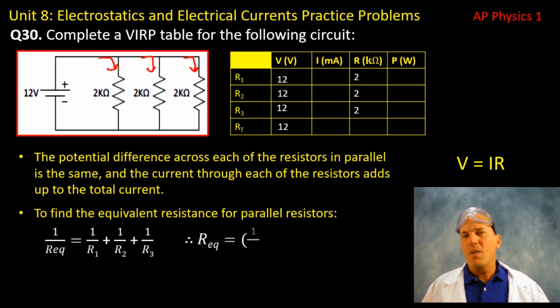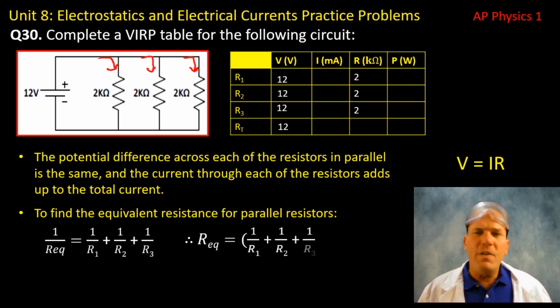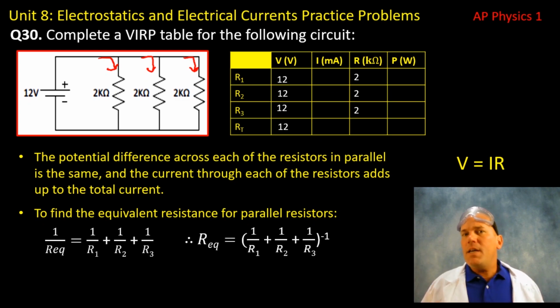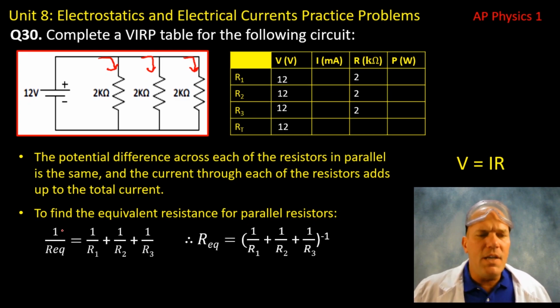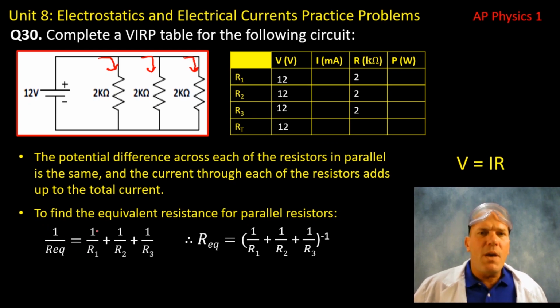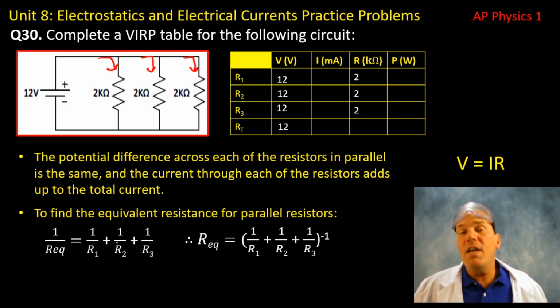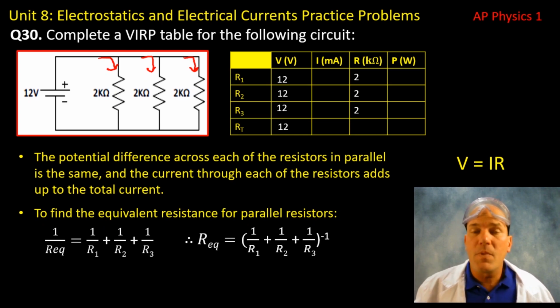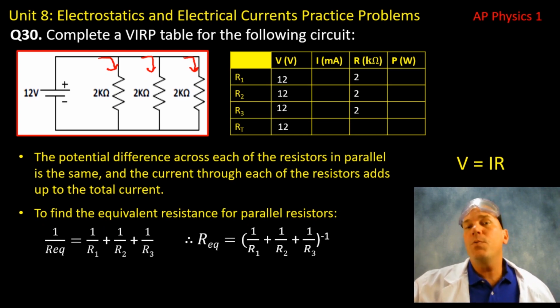So that makes it quite simple to find for this particular one, because now we know the voltages for all the resistors. Now, unlike what we saw in a series combination, we cannot simply add up these individual resistances. For any combination in parallel, we need to use this inverse equation, in which the inverse of the equivalent resistance is equal to the summation of the inverse of the individual resistors, R1, R2, R3 in this case.